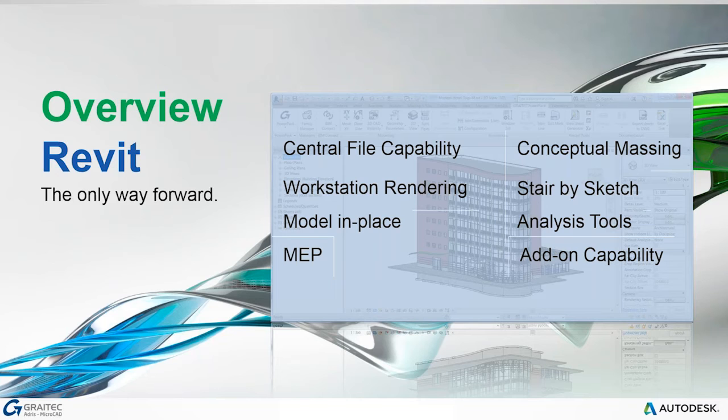And finally, the other big one, of course, is add-on capability. We talked a little bit earlier about things like the Kobe tool, add-on tool for Revit. This is a plugin, and only the full version of Revit can have plugins. So in Revit LT, it's just not available, and that's been pretty normal for as long as I can remember. There's always been a difference between the LT products and the full products. In LT, you can't have the add-ons. In the full versions, or whatever the software is, it has the API that will allow you to add bolt-on programs. So those are the main differences between LT and the full-blown Revit. What we can see on here are all the items that the full Revit has got that LT does not. There are some other issues, other little bits and pieces as well, but these are the main ones.